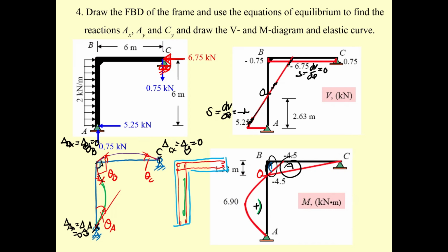Okay, and also put the extra steel over here due to the negative moment, and put the extra steel over here, if this structure is reinforced concrete. Okay, and again, for the stirrup, negative or positive is okay, the same way.